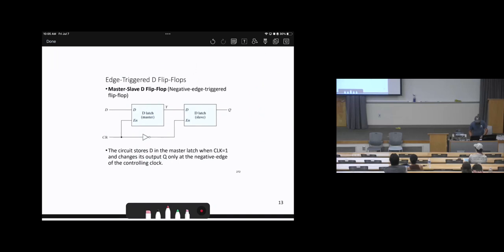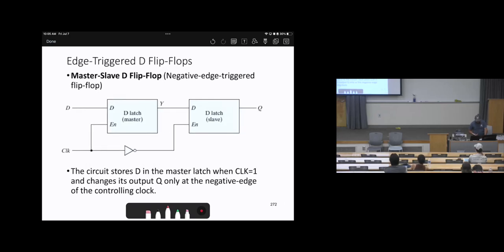How to create the flip-flop? Actually, we can create a flip-flop, for example a D flip-flop. It's based on D latch, and it's a combination of two D latches in series. Then we can create the flip-flop. We are making the problem more complicated step by step. First, I discussed how to create the memory, or how to store the data, by having two inverters.